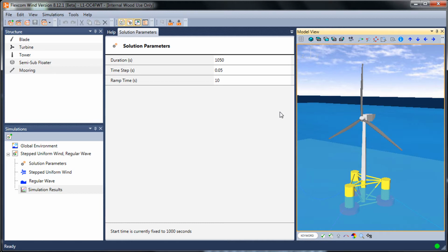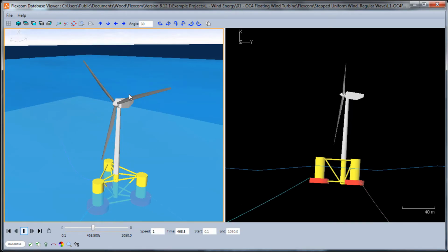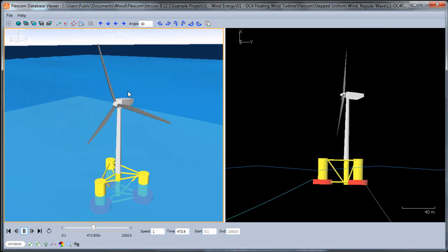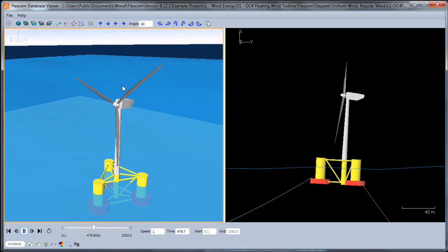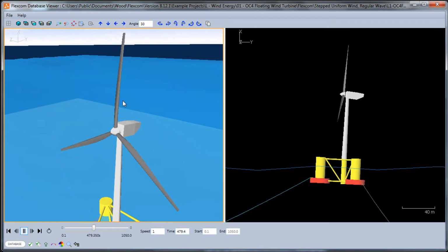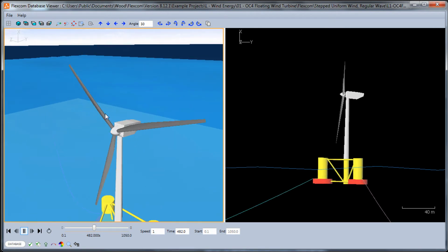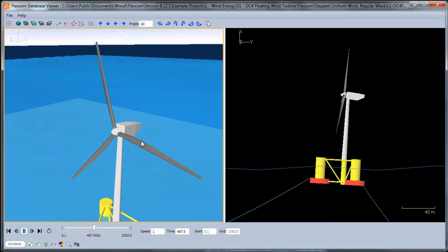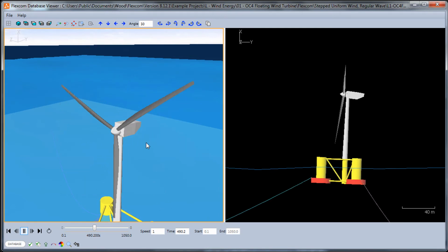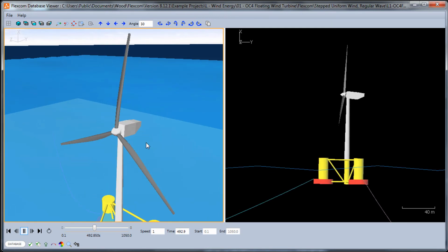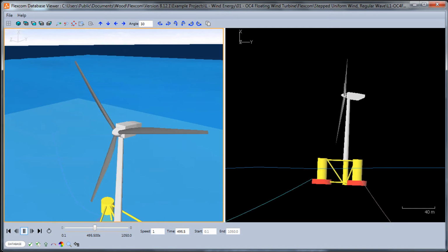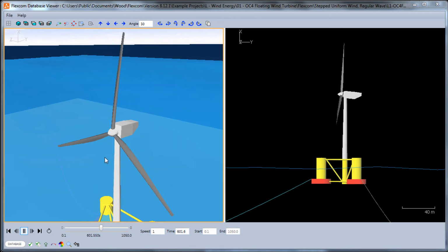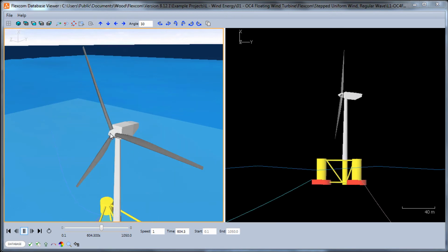That's just in terms of the front end of the user interface. In terms of the theoretical, the finite element representation of the floating wind turbine, we have one or two limitations which we need to address also. Namely, the blades themselves in the Flexcom solution are assumed to be rigid, so we do not consider local blade deformations under the action of wind loading, which can in turn affect the aerodynamics on the spinning blades if the blades are themselves to deform. Also, the effects of the rotational inertia of the spinning blades is currently neglected in the Flexcom solution.